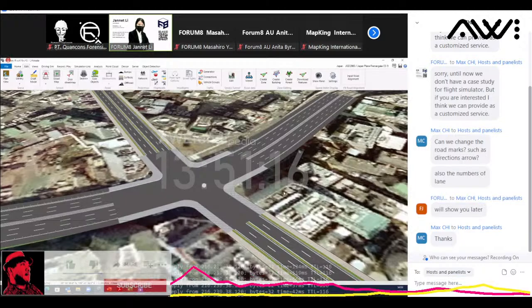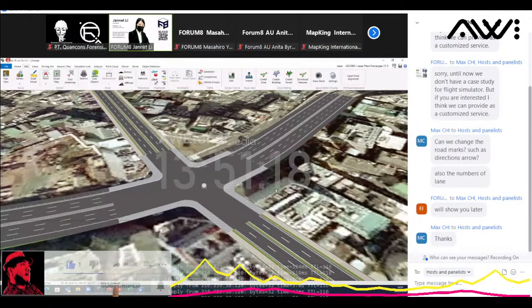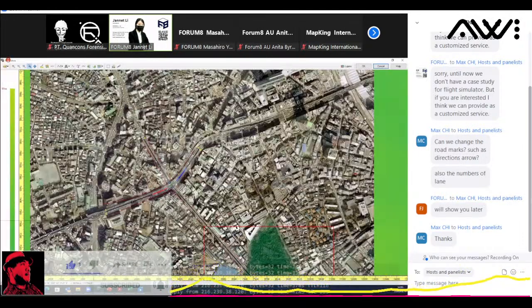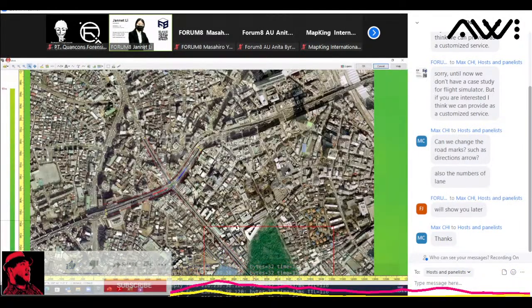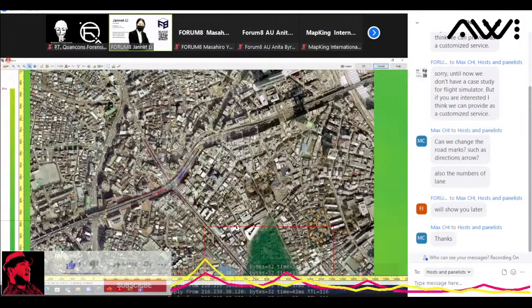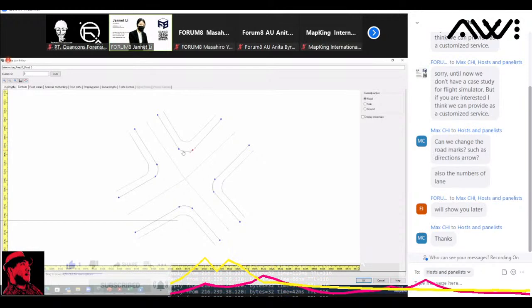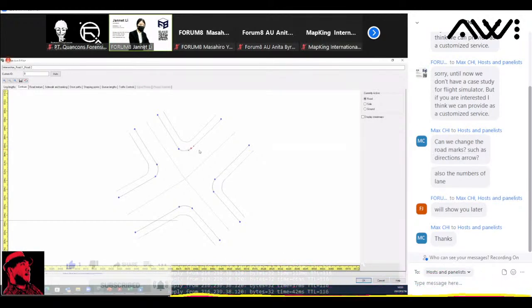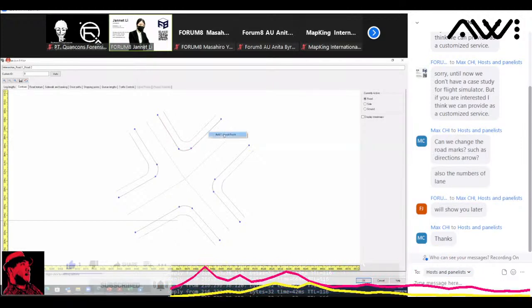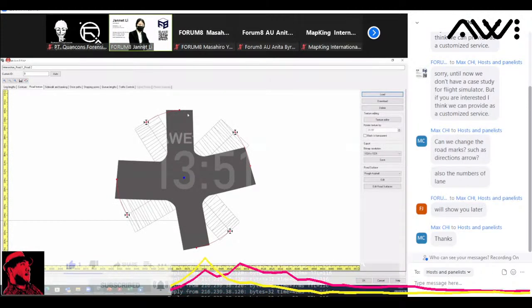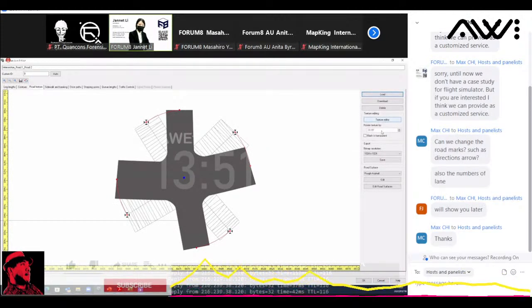All right, let's edit it inside the edit intersection. So we have so many options here. You can add in roundabouts, you can change contours of the roadsides, the shape, basically, of the corners. You can change the texture of your road for this part of the intersection.